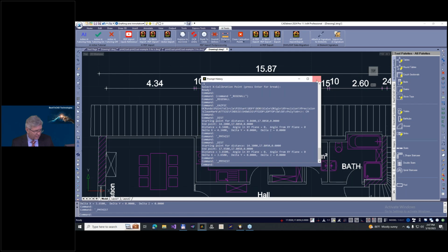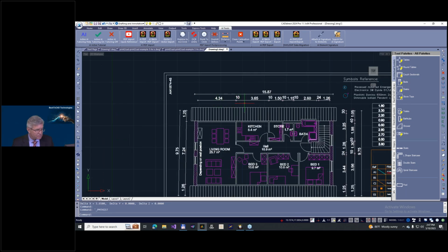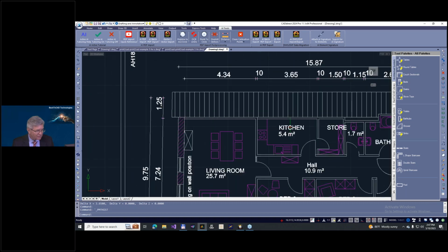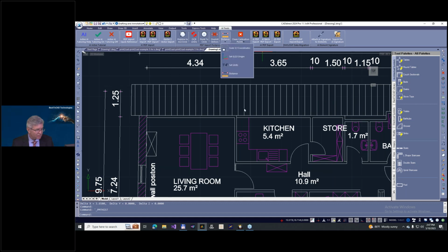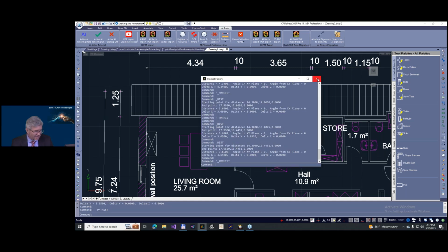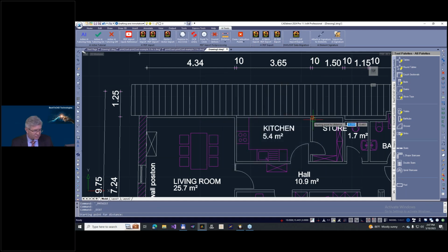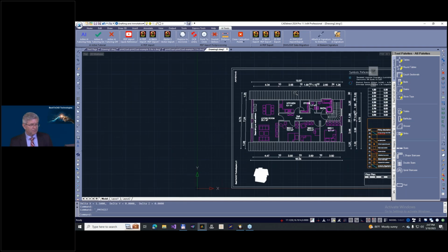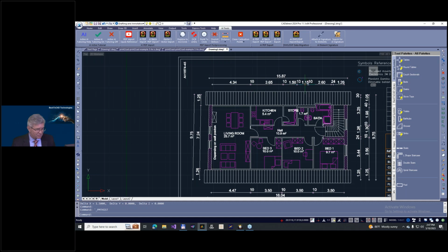365. Can you see? But we calibrate not only this part, we calibrate the drawing itself. Now, if you measure a distance, for example, from here to, I need a vertical distance, moment, from this endpoint to this endpoint, look, we got exactly 365. And if you measure the distance from here to here, it is exactly 1.5. Like this, with the help of these dimensions, we were able to calibrate the full drawing.